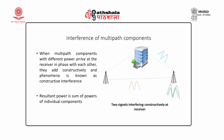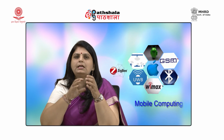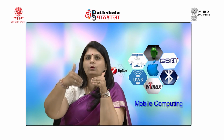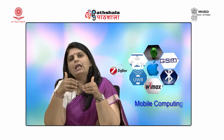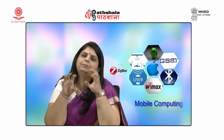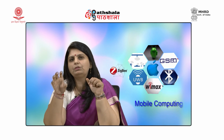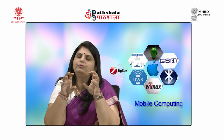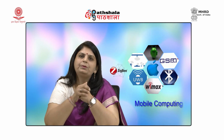Also, when these multipath components reach the receiver, they will interfere with each other. As I said, they are overlapping in time, they are overlapping in amplitude, and they are coming in different phase. So, sometimes they may reach in phase. What do we mean by in phase? The phase difference between the two signals or the two waves is 0 degrees. We have discussed the phase shift in the previous lecture.